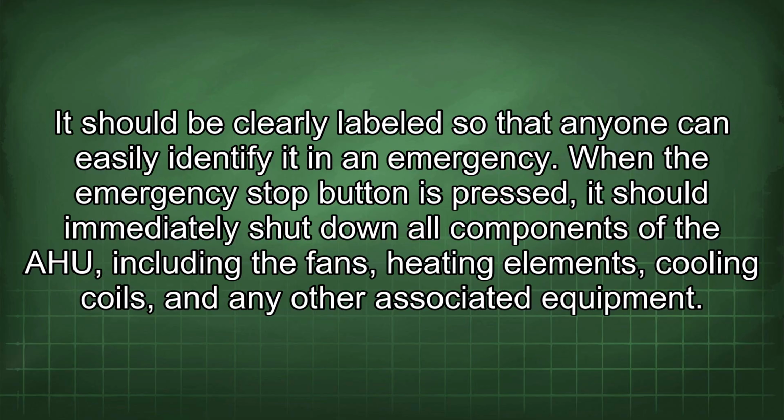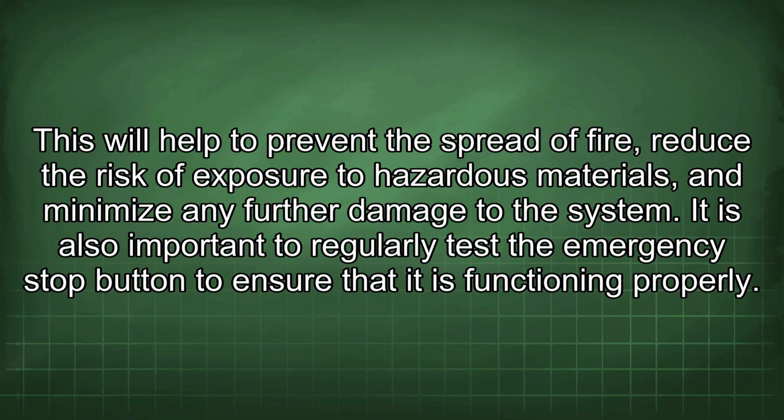When the emergency stop button is pressed, it should immediately shut down all components of the AHU, including the fans, heating elements, cooling coils, and any other associated equipment. This will help to prevent the spread of fire, reduce the risk of exposure to hazardous materials, and minimize any further damage to the system.